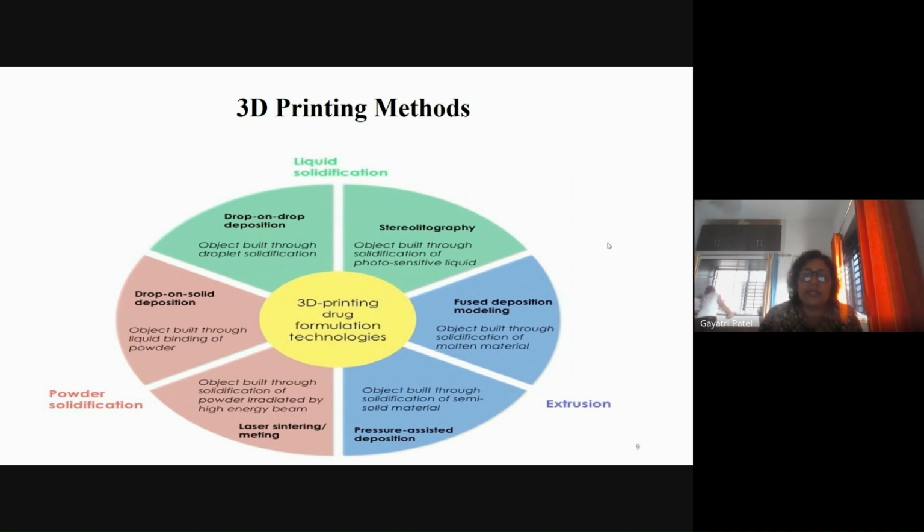But for healthcare applications, one of the biggest challenges is biocompatibility, or the degradation profile of that particular filament. We also can't have the drug itself in the filaments, so we require specific extruders to first fabricate filaments that are a composite of drug and polymer, and then process them into the desired shape. We can consider that one of the challenges.